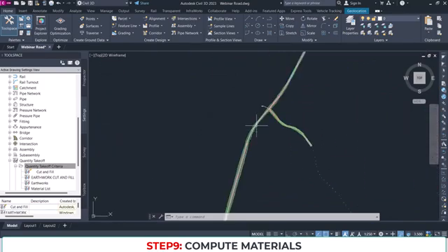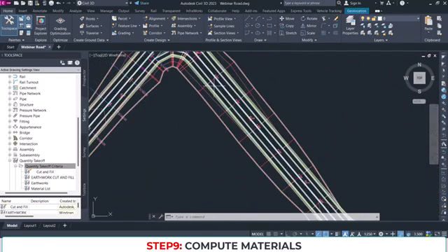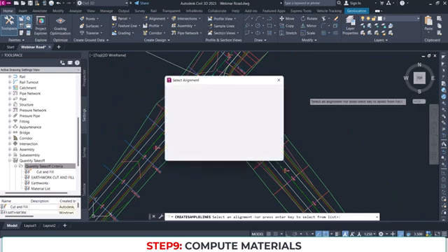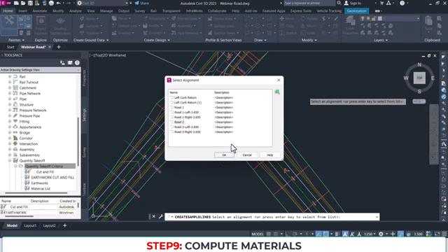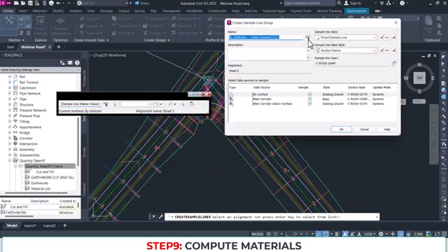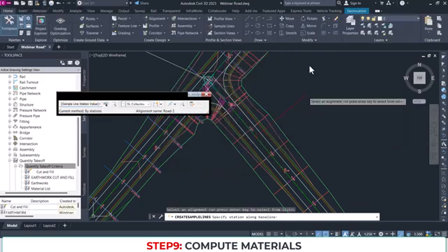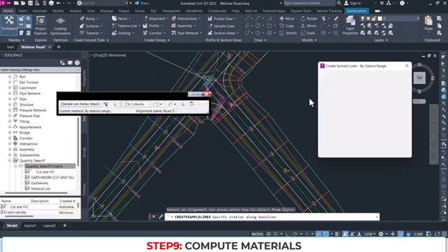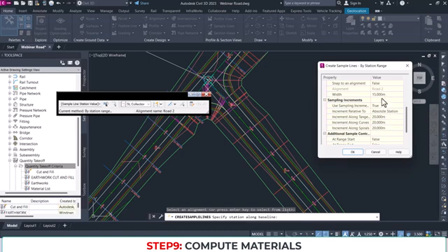We also do the same thing for road 2, by creating sample lines. We go to sample lines, press enter, click on road 2, and press OK. Everything is by default. Now go to by range of stations again. Civil3D is merciful and brings back the previous settings.